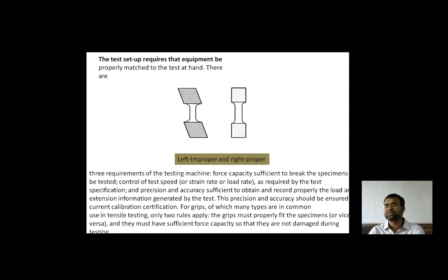Extensometer is a device which identifies the elongation in the material, and that is why this particular point is to be mentioned here. The elongation of that particular material is to be identified by this equipment, and the elongation process which is happening in the material is recorded on the stress strain curve which is drawn by that particular machine.